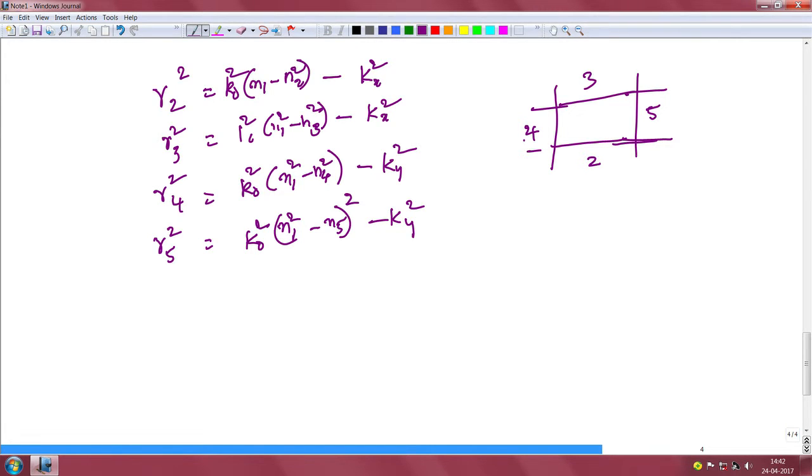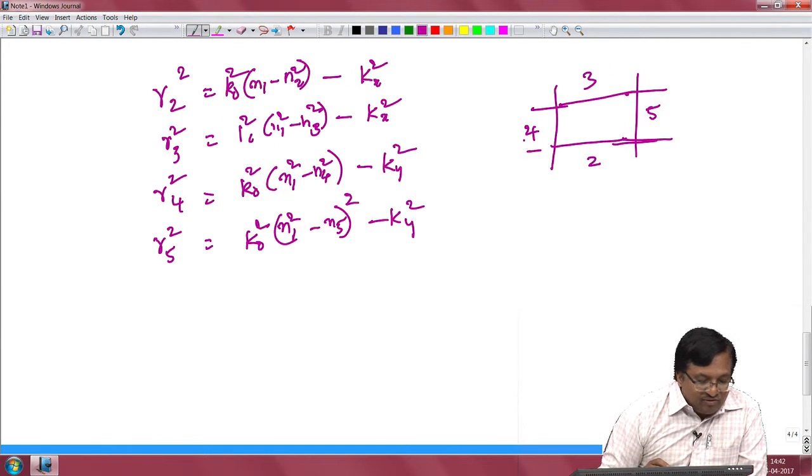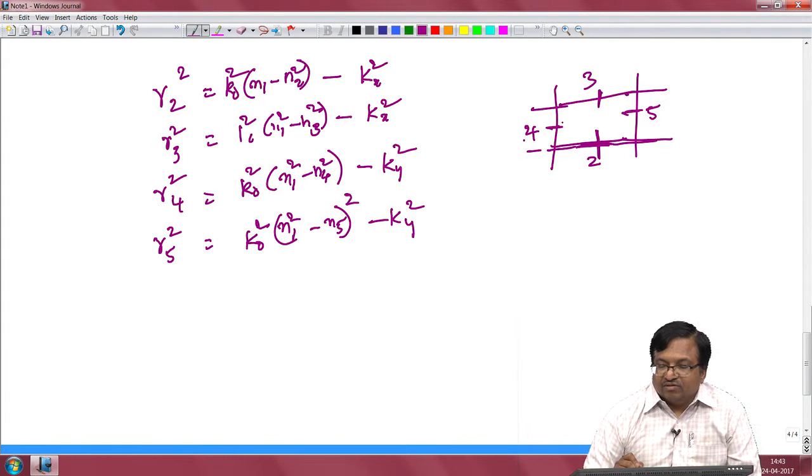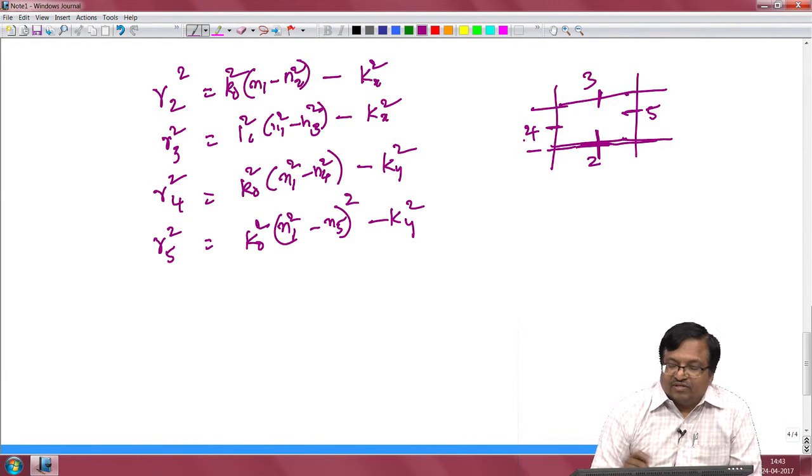So, in order to find all these constants, we need to have the boundary conditions, that is the fields at the interfaces. We can say that the fields are continuous, as we did for the slab waveguides. We can force the fields to be continuous across the boundaries, and also the derivative of the fields to be continuous across the boundaries. Just recall that the derivatives of fields could be related to the magnetic fields if the fields are related to the electric fields.